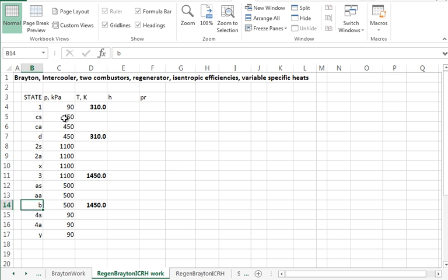And then we walked through the pressures, did we not? And so each of these pressures we're able to say, oh, it starts at 90, it's 450, then it's 1100, then it's 500, then it's 90 kilopascal for the pressures. And then I like to go and put all of the temperatures in that I know. So I know T1, I know TD, it's after the intercooler, it's cooled back down to 310.